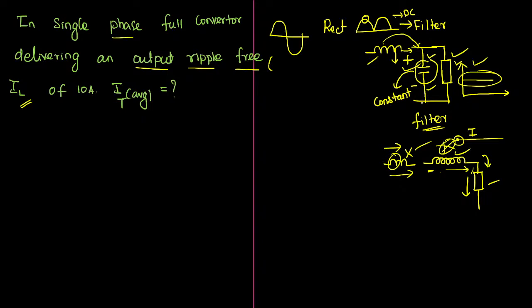இந்த பேசிக் காம்பினேஷனை வச்சு தான் சாப்பர் சர்க்யூட்ஸ் டிசைன் பண்ணிருப்பாங்க. நீங்க சாப்பர் சர்க்யூட்ஸ் எல்லாம் படிச்சீங்க அப்படின்னா அவுட்புட்ல எல்லா இடத்துலயுமே கெபாசிட்டர் இண்டக்டர் போட்டிருப்பாங்க. The reason is, we are trying to maintain it ripple free because we are trying to change the DC voltage. DC வோல்டேஜோட லெவலை நம்ம சேஞ்ச் பண்ணும்போது, ஒரு லெவல்ல இருந்து இன்னொரு லெவலுக்கு இன்க்ரீஸ் பண்ணும்போது கண்டினியூஸ்லி டிரான்சியன்ட் எஃபெக்ட் இஸ் தேர். I don't want these things.